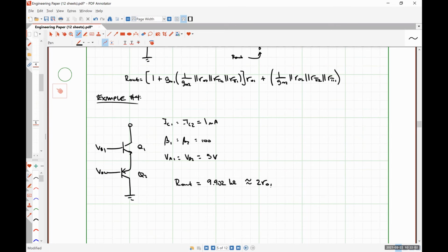So when you're going to cascode anything, when we're going to be doing a whole heck of a lot of it, you always want to make sure that you're cascoding with a same technology transistor, right? So if you use an NPN, you degenerate it with an NPN. If you use a PNP, you degenerate it with a PNP. If you use an N MOSFET, you degenerate it with an N MOSFET, etc.